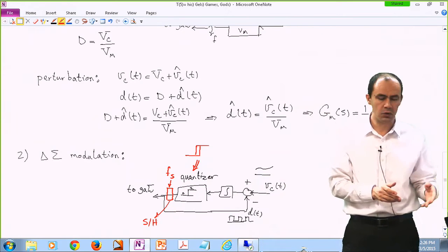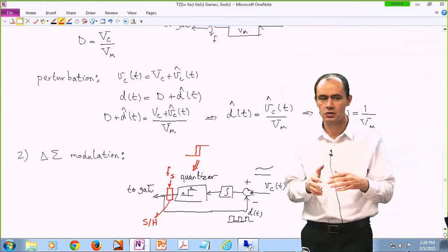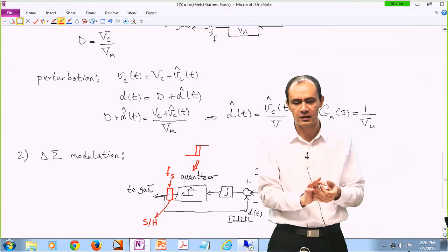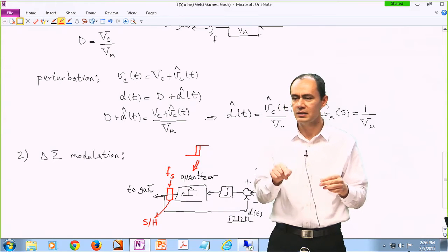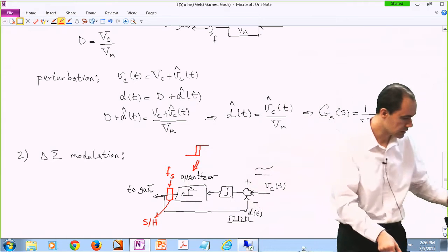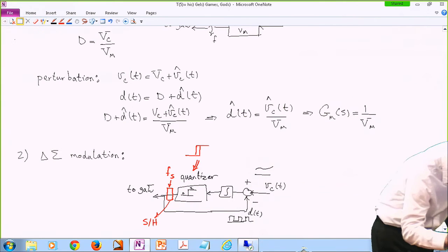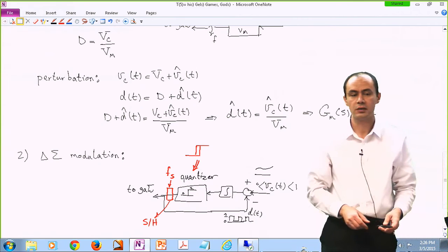So there are papers actually looking into this. Is it more effective than the PWM scheme? There are some inverters that operate based on this. So you don't have a fixed frequency or a PWM signal. You just look at your pulsating signal that is applied to the gate versus your compensation signal. So assuming that this is between 0 and 1, these levels are also 0 and 1.